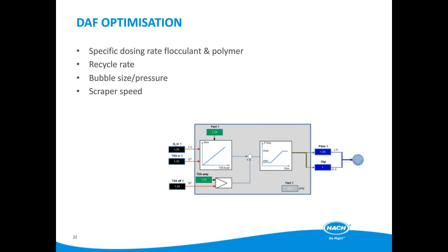It is our experience that the operators of wastewater treatment plants are busy people, and they're only able to make 1 or 2 tests per shift to adjust the chemical addition to a plant for optimization. Between those samples, the influent strength goes unmonitored and could fluctuate wildly. This is the reason for applying real-time control to any process. You can only control a process if you can measure its key parameters, and to control it efficiently, those key measurements need to be made frequently to cope with variations of incoming load.